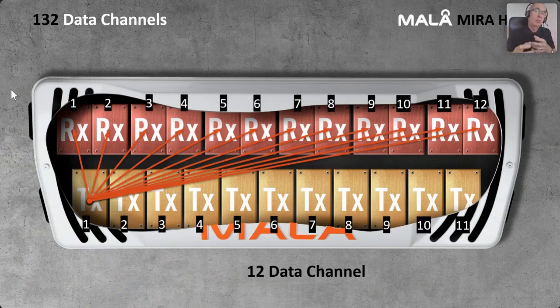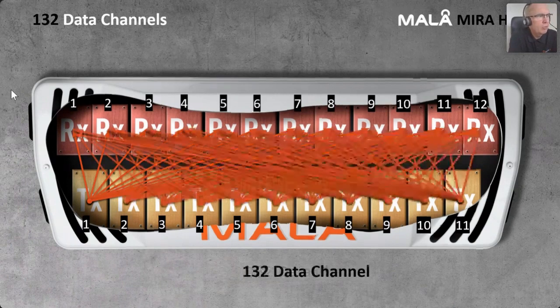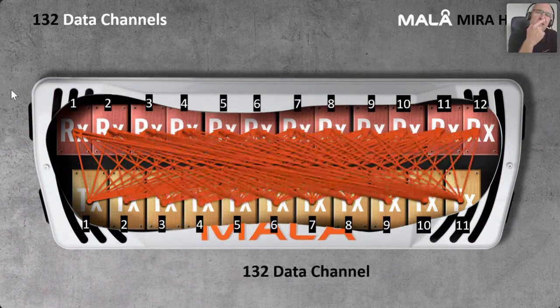This enables you to do some other things, not just utility and archaeology. We can start to look at moisture mapping of the subsurface, and this can be used for analysing road construction and defects in roads, particularly. So that's 12 channels there, and if I then run from the second and the third transmit to all the receiving antennas sequentially, I build up this bank of data, and that will give me my 132 data channels.